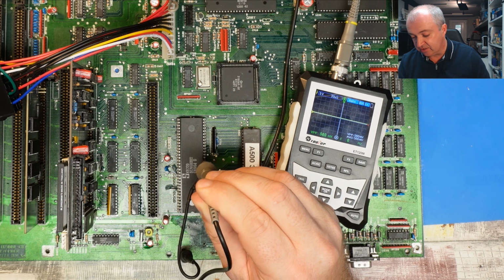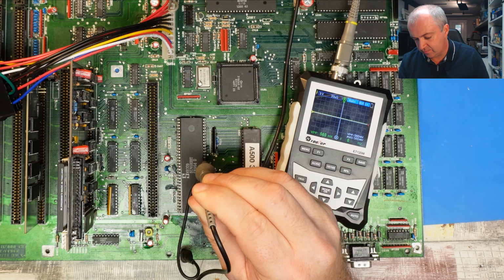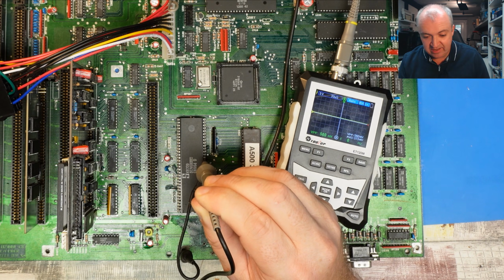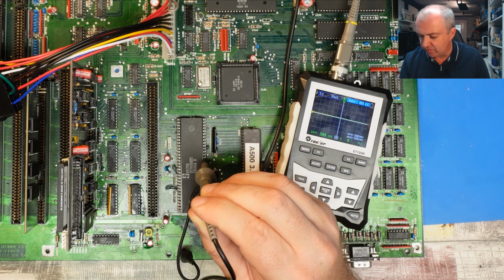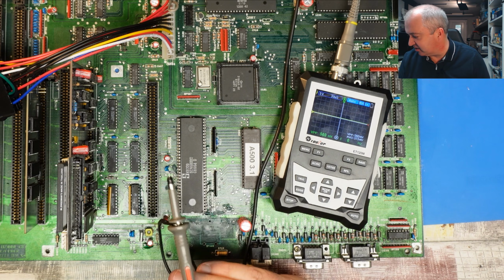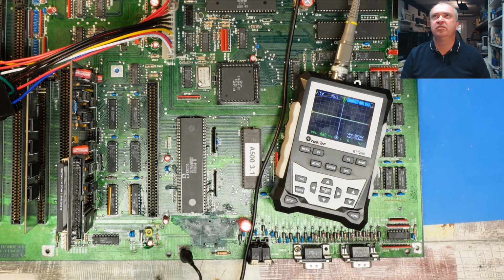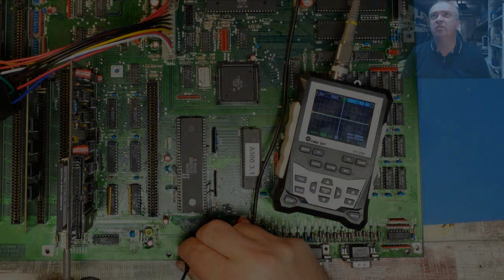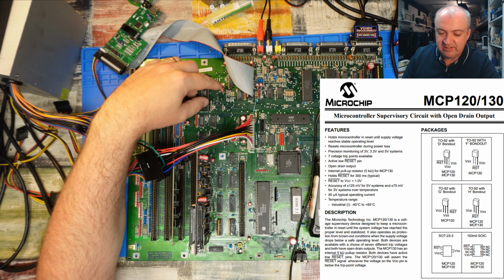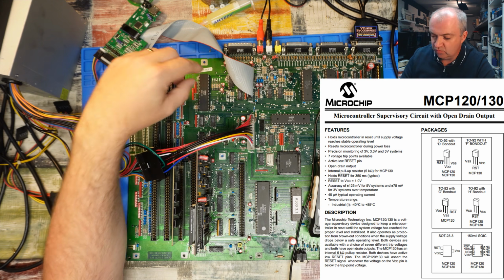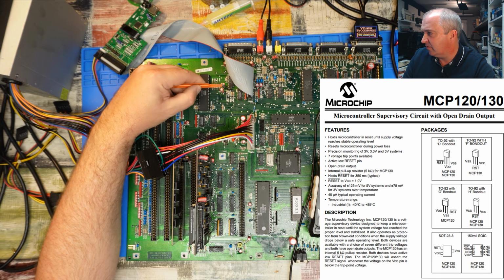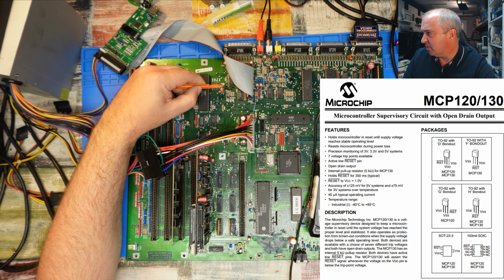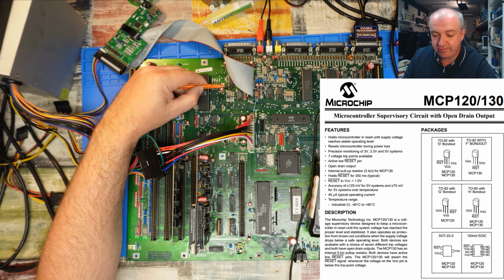Let's just do a power cycle. Yep, that ain't working. We may just have to remove that and put the diode back in. Although, let me just quickly check the datasheet for that part, just to be sure I haven't put it in backwards. So ours is the D type package, and we need to connect that up with ground on pin 1, VDD or the supply voltage on pin 2, and reset or the output on pin 3.